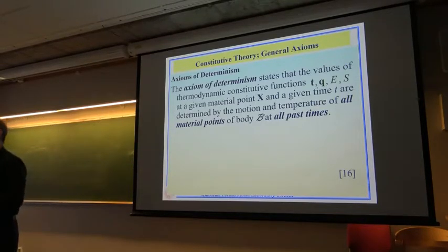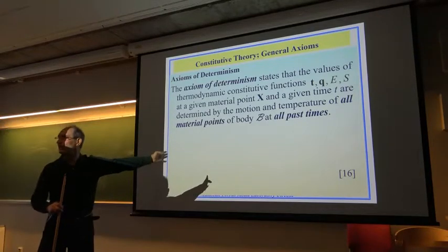If you take the equation, Fourier's law, Fourier's law says the heat flux at any given point is proportional, with a constant, to the temperature gradient. Temperature gradient not 10 days ago, not a minute from now, but the temperature gradient at that time. And temperature gradient means actually the heat flux depends on the temperature of that point and the point next to it. So it depends on 2 points. So heat flux is a very, very simple expression compared to what I'm saying here.